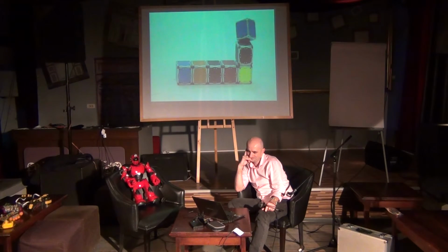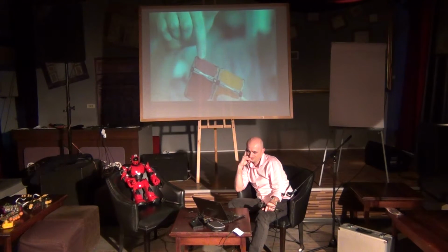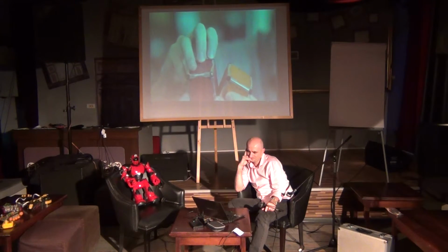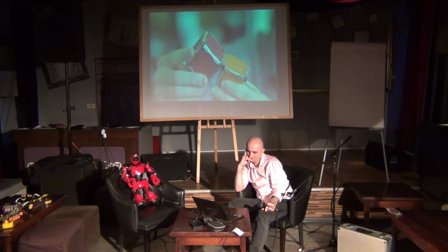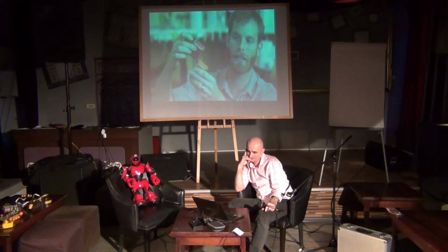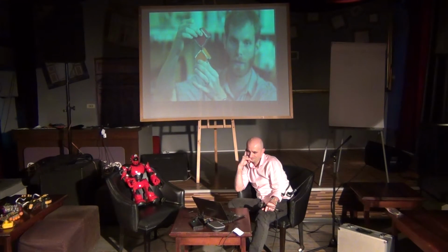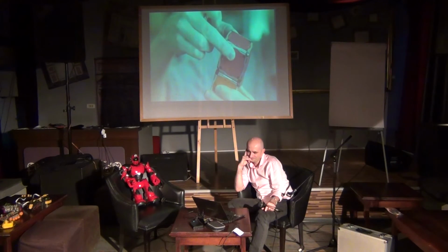The magnet system in the cubes is one of its key features. So we have face magnets. There's 8 face magnets that provide some coarse alignment. And then there's these edge magnets, which are free to rotate. And the key is that when a cube starts rotating, the edge magnets actually get closer to one another. So if we start from this configuration and we break the face magnets free and start rotating, the edge magnets actually get a little bit closer due to the fact that the edge is slightly cut back or chamfered. And as a result, you form a very strong bond between cubes, which allows them to stay attached as one is rotating into a new position. It continues rotating, the face magnets provide alignment, and it snaps into place.